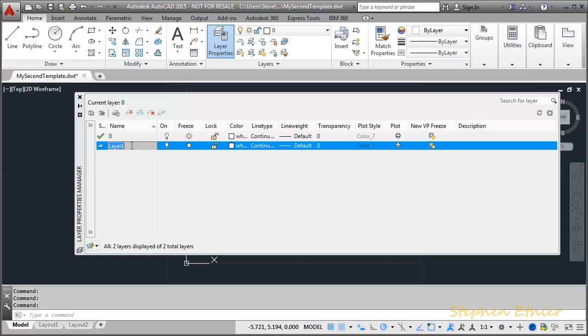Like drawings, layers should have names that give the user more information on what will be contained on the layer. If this was to be an architectural drawing, you would give the layer names like walls, doors, windows. But for our video tutorials, we want them to be as universal as possible. So we are going to assign them typical drafting terms to the layers.